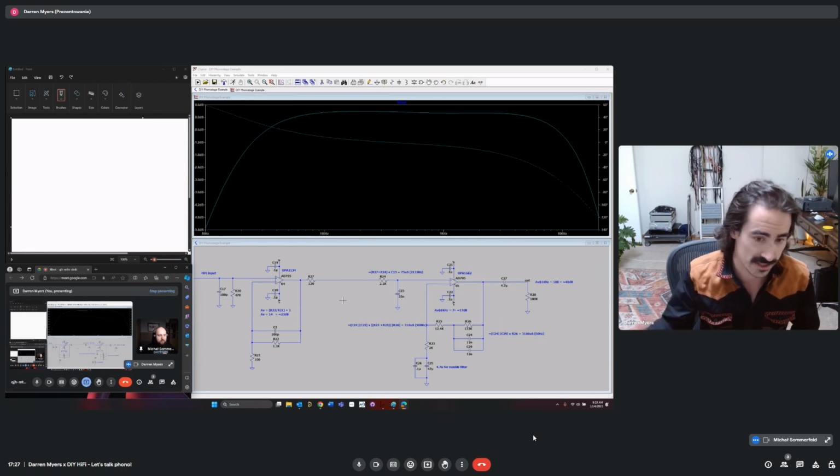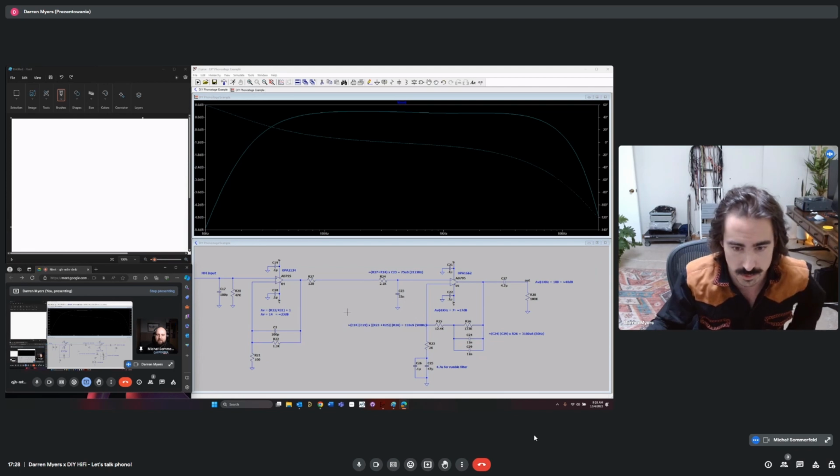They just want a chip that's going to work no matter what and not cause a bunch of fuss. So that's one of the reasons that phenomenon exists. There are other reasons, but that is one of the main reasons monolithics don't always have great open loop gain at high frequency.